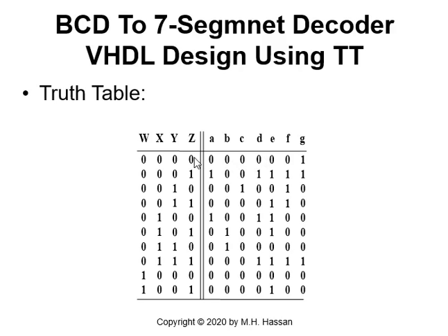Now, if we would like to display 0, and if the 7-segment display is common anode, we need all zeros for all the segments except the segment G, which is the one in the center. We need 1 to not get light out of the segment. So by this, we will get a 0.